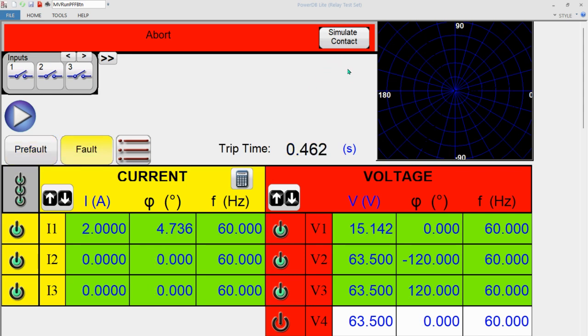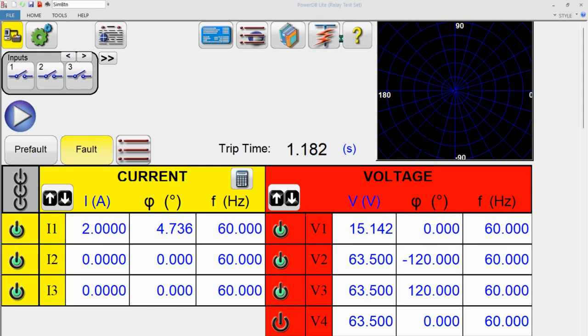Based on that selection, we put in the values, and when we press play, the fault values are applied, pre-fault and fault. If the relay operates, we can compare what our fault impedance value and fault percentage set was and what is measured. So it's easy to compare. It's quick manual testing to measure the fault location.